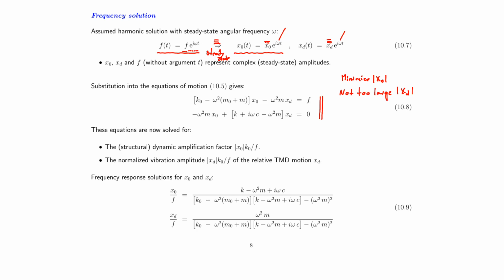Consider you have a pendulum damper inside an offshore wind turbine. There's only a limited amount of space. The radius is actually the maximum vibration amplitude of your pendulum. So in many cases, this is also a concern. But the structural deflection is our main objective. And next, we would also like to minimize xd.